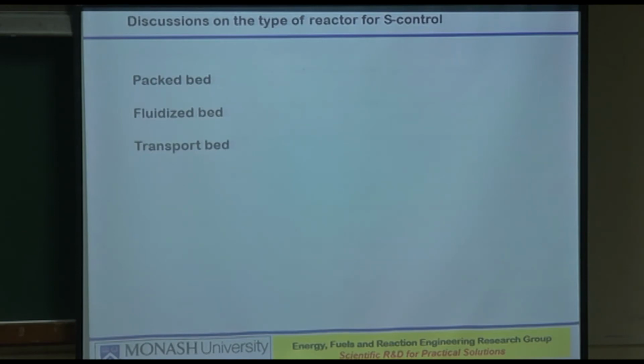So it all boils down to what size of filter particles you are using. If you are using a filter particle which is quite large and still capable of doing the reaction between hydrogen sulfide and that particle material within a reasonable time, go for packed bed. Easy to load, easy to clean, easy to operate. But that often doesn't happen. Then you have to consider, okay, this is the supplier of my sorbent for the next 10 years. You need to have that contract. Otherwise, if the manufacturer all of a sudden goes bust, then you are in trouble. So you need to have a consistent supply. So depending on that, you decide whether you will be designing and operating it as a fluidized bed or as a transport bed.